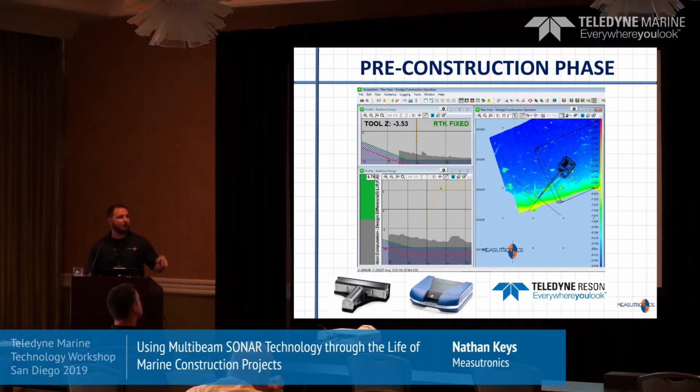It's another contractor here. So this is like a marina, and so on the right-hand side, you can kind of see the grid model there, and there's some logs kind of right where the excavator is there. You can see there's some sort of big green long items there, those are logs. And so the idea was they're going to dredge this out, but before they do, they have to remove these logs. And so they did a survey, and we were able to locate all the logs with the survey, so they also have guidance on this excavator, so they can move the excavator right over the surveyed log, pick it up, get it out of the way so they can continue dredging.